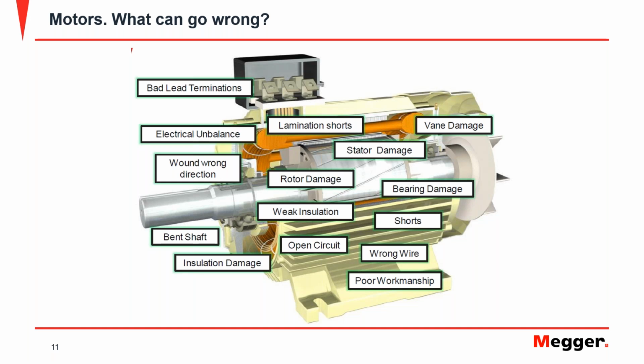I call them active tests, which are the types of tests that you do when the machine is not in operation, the static types of tests that we talk about, because during these tests you inject a magnitude, be it a current or a voltage, into the machine, and you measure the results of the injection of that magnitude into the machine. You do the injection yourself.